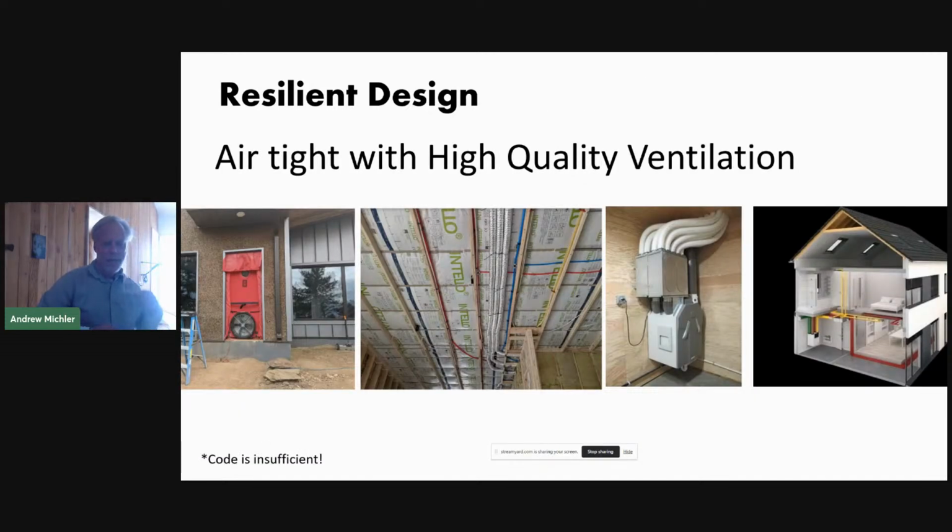And then the air tightness side of things. For Passive House, we look at what we call a dedicated air barrier system. And if you look at that middle slide, it says Intello in there. That's a material that's taped very, very tightly. It's a fabric-like material that has the ability to intelligently work with vapor in the house, so we don't get condensation building up. But at the same time, it's airtight, and it wraps all the way around the building.